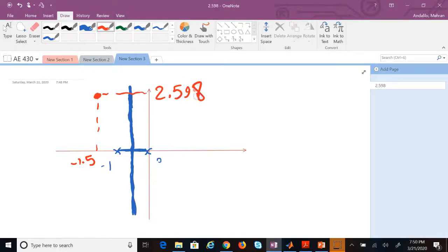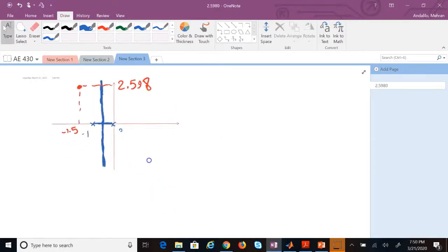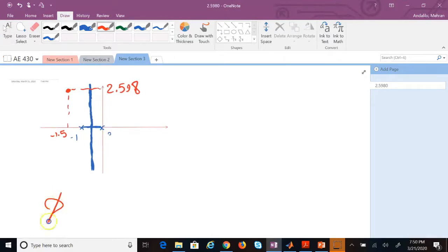So it says the angle deficiency phi is equal to 180 minus the sum of the angles from zeros of the original transfer function to this pole. Now the original system does not have any zero, so we are not going to add anything, but we subtract from it the angles of what?